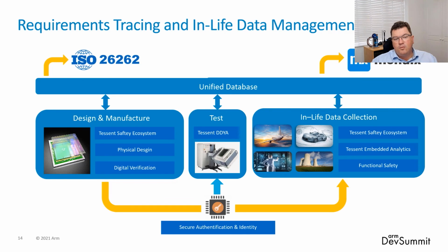So we've talked about the different types of data that can be generated on chip and how we can manage that with the Safety Island and the Safety Manager CPU. Typically, with this structure, we are making reactive decisions based on individual occurrences within that particular device. However, if we're able to collect the data from that device alongside the same data from millions of other devices all running the same software in the field, we can provide a wealth of data to do additional layers of analysis.